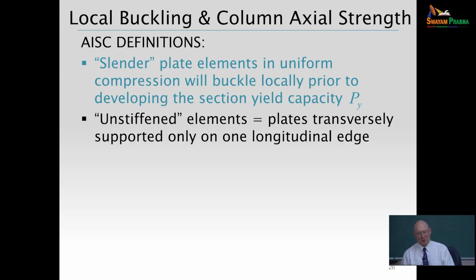Well, I brought up unstiffened first here. So that would be like a flange of an I section. One of the edges is free, the other one is supported by the web, and so that's an unstiffened element. In the Bridge Standard in the Americas, we'd say that's an element that is supported on one longitudinal edge.